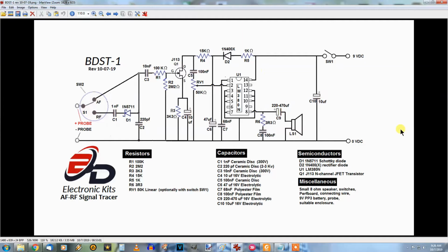The problem we're having is with this circuit here, the input circuit. What it is basically, we're overloading the audio before we even get to the audio amplifier, and in a bid to get as much sensitivity and gain out of the circuit, we have kind of lost track of the fact that with a stronger circuit it's going to distort.